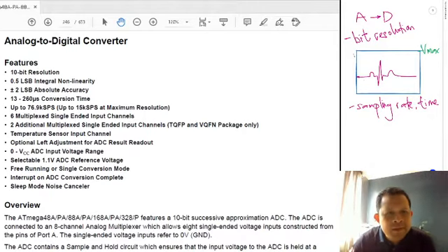Every ADC will define the maximum voltage, or you can do some programming. You have to refer to the manual of the ADC to see if you can program the maximum voltage to certain levels. We will look further into the ADC later, but now we want to get the concept first. And over here below is 0 volts.